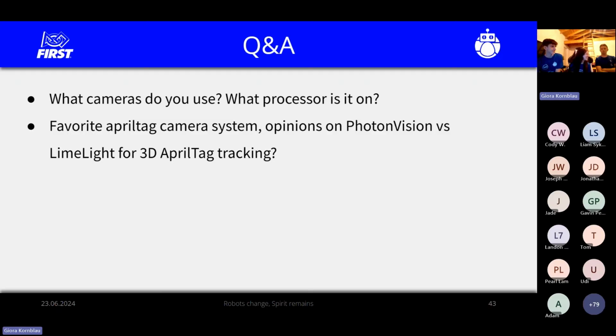Why don't we use the absolute encoder during the match, for the swerve heading? We said at the beginning that we use them only for startup, because we don't need them afterward. The Falcon encoder is accurate enough and doesn't drift, so we can use that throughout the match. We do need the absolute encoders, because otherwise we'd start the modules not aligned and we wouldn't be able to drive. But we don't need to use them during the match.